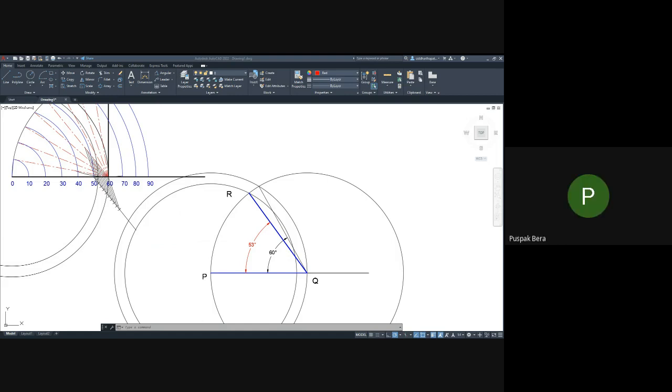Yes, sir. Okay, so once you have drawn the 90-degree angle, I need you to trisect that angle. Now, trisecting a 90-degree angle is quite easy. So you see, the moment you drew that 60-degree angle, which is basically intersecting the arc with the radius of the arc itself, that way you get 60-degree angle. So the other portion of the angle is 90 degree minus 60 degrees, which is 30 degrees, which is one third of 90-degree angle.